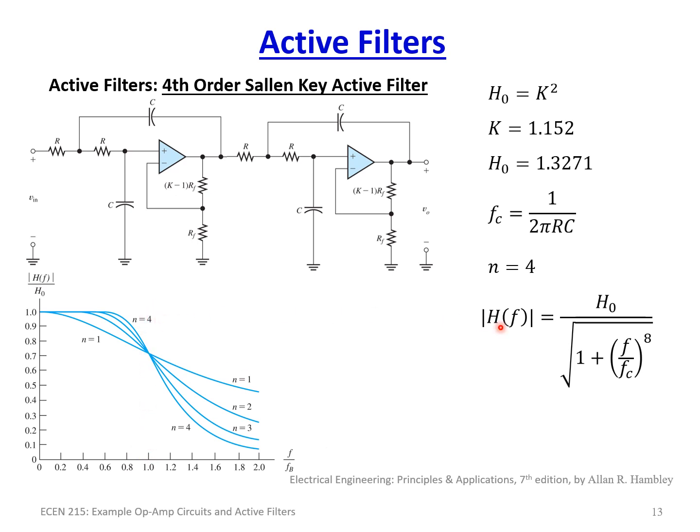Then there are different transfer functions for that, but they don't have as flat a pass band. The nice thing about the Butterworth is the pass band is very flat, allowing the signal that you're actually receiving to be of quality, and you can trust that it is going to be the value you're reading.